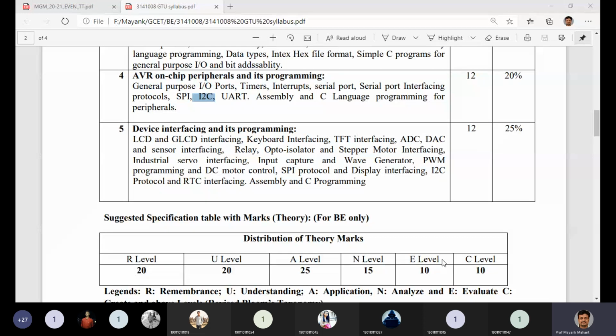In serial communication, the data is transferred in series, and in parallel communication, the data is transferred in parallel. It means 8 bits can be taken at an instant in parallel communication. So parallel communication is the faster way of communication. Serial is the slower way, but the number of interconnection lines creates a problem.